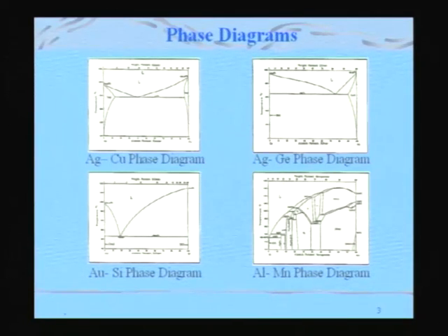You go through another stage called epsilon carbide, which people call Fe2.2C, whose crystal structure is hexagonal, which is close to that of the FCC structure, which is the original structure from which the martensite is obtained. So as a result, one can easily say that the formation of HCP will have a lower activation barrier than the formation of the orthorhombic Fe3C, which is the cementite.